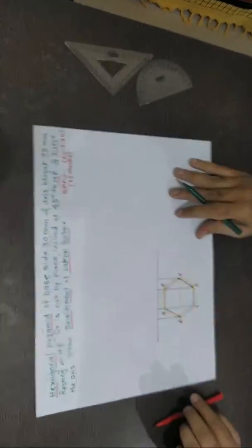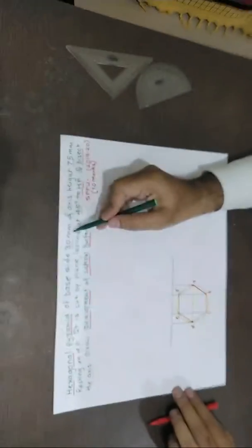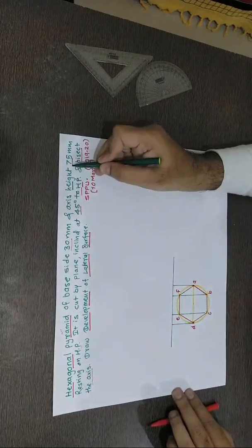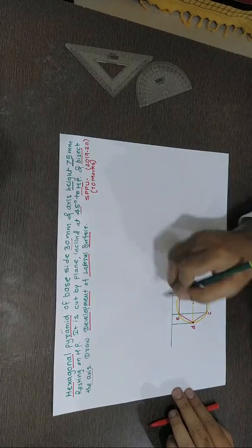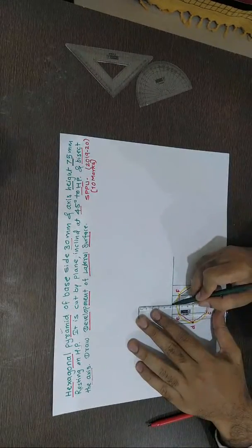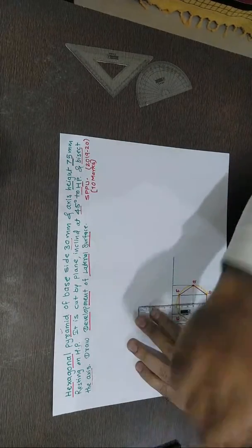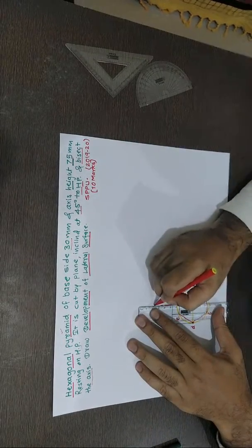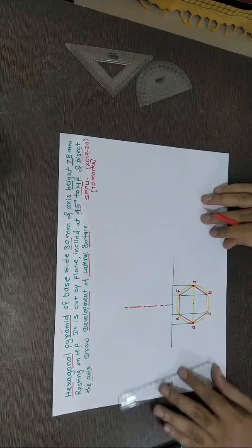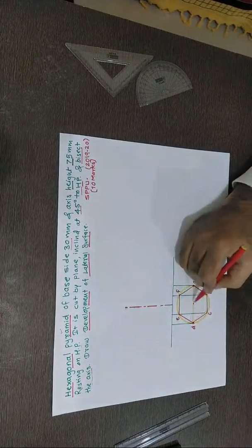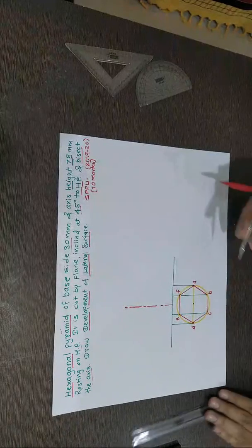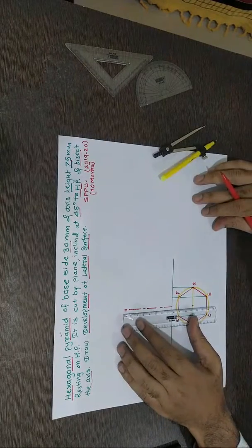Now, important thing is in the question, it is clearly mentioned this base side is 30. So this is 30 all. Axis height is 75 mm. So I need to draw first the axis as it is a pyramid. So very important, I'll project this axis point also. I'll draw the axis by a center line symbol. You can see clearly in this video. So now this is the axis I am drawing by taking a projection of the center of the circle, of course. Now on this you mark the axis height as 75 mm.